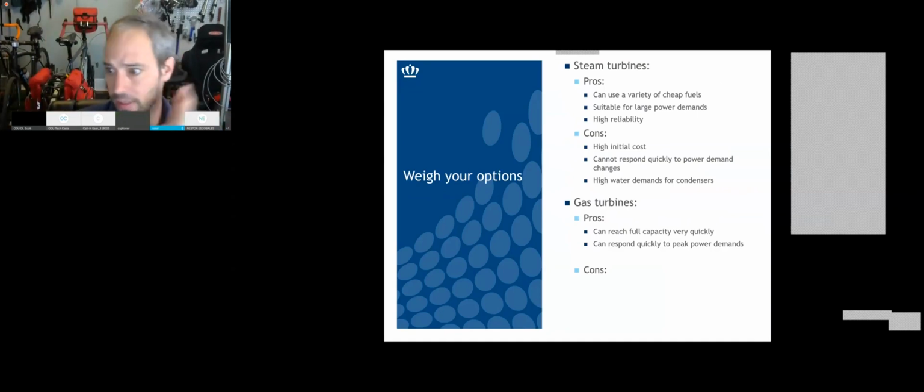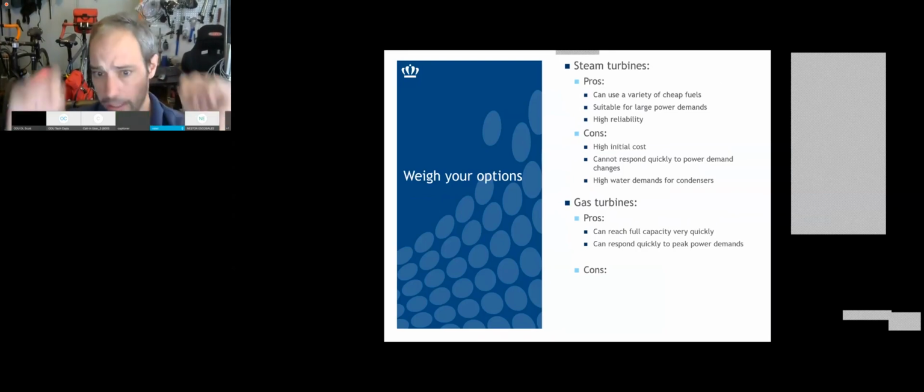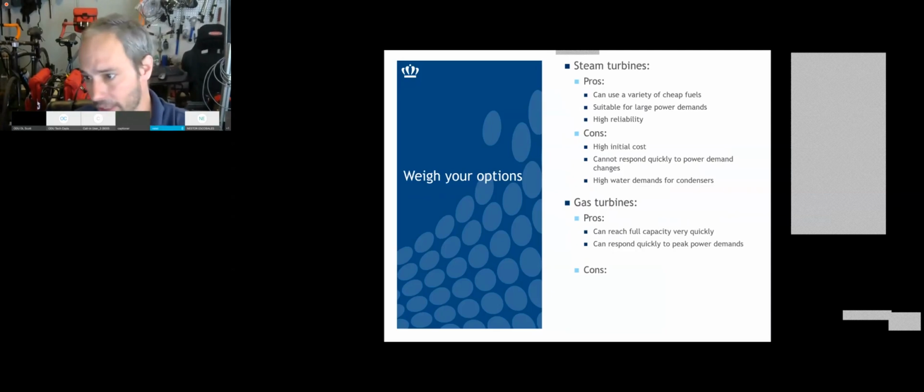It's like a car almost. It's not the same kind of engine, but it can spool up and spool down really quickly because all you're doing is throwing fuel and air into a combustion chamber. It explodes and it rushes through the turbine. Steam power plant, you have to change the amount of flow rate of water you're trying to boil, and that takes time. Combustion is very quick.